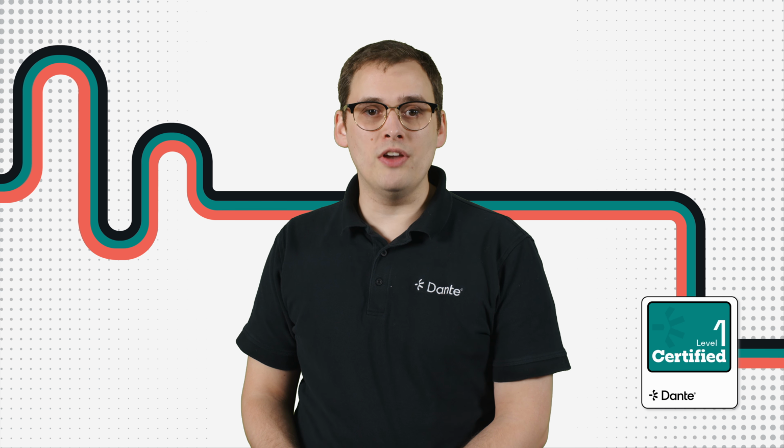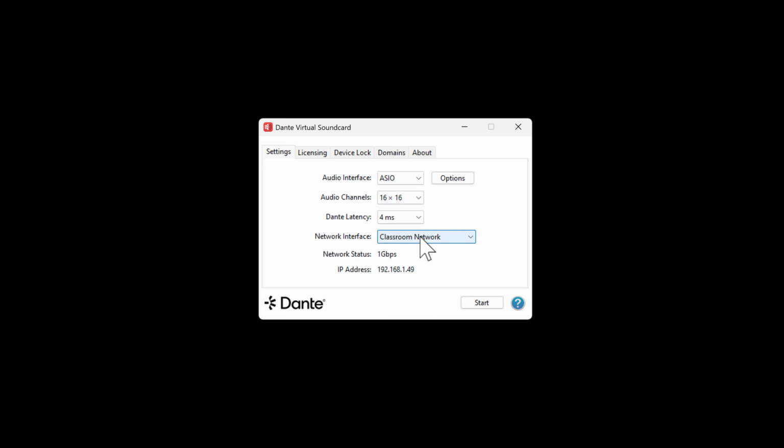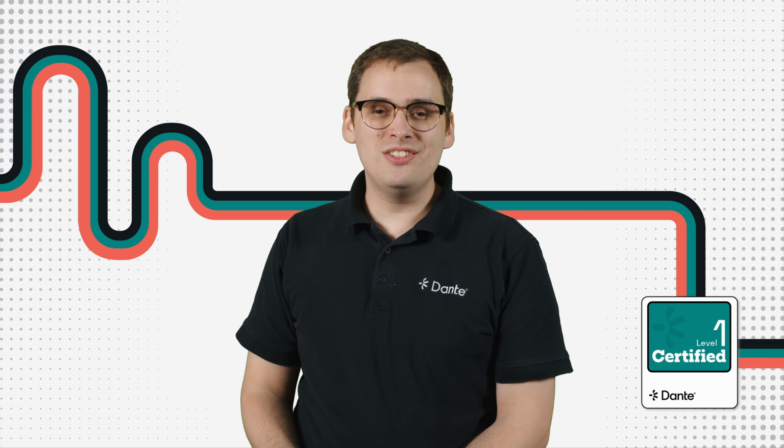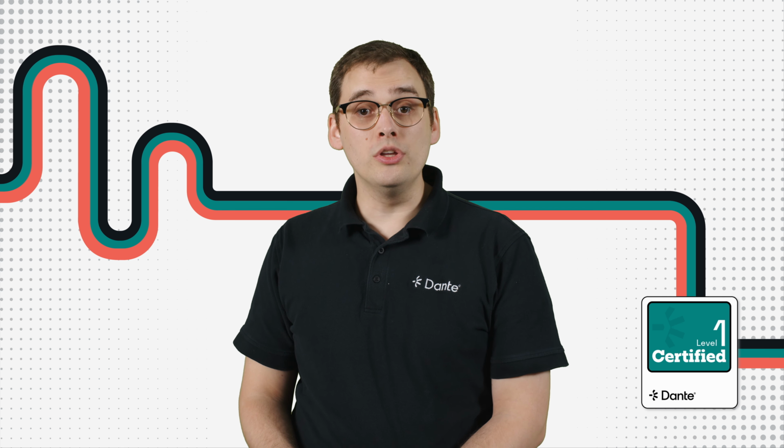For the DVS Pro version, 128 channels will be available at 48 kHz and 96 kHz, but only 16 channels at 192 kHz. Next comes the Dante latency section. In this drop-down menu, you can configure the device's latency at either 4, 6, or 10 milliseconds for standard DVS, and up to 40 milliseconds with the DVS Pro version. Any Dante device receiving audio from this instance of Dante Virtual Soundcard will use this value.